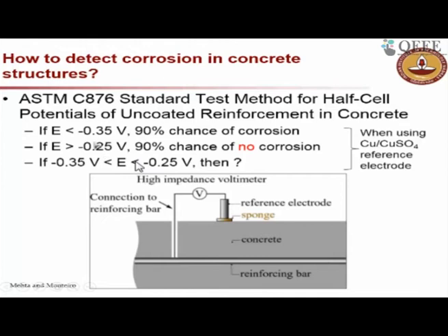There is an ASTM standard which says that if the potential is less than minus 350 millivolts, or 0.35 volt, there is a 90% chance of corrosion.